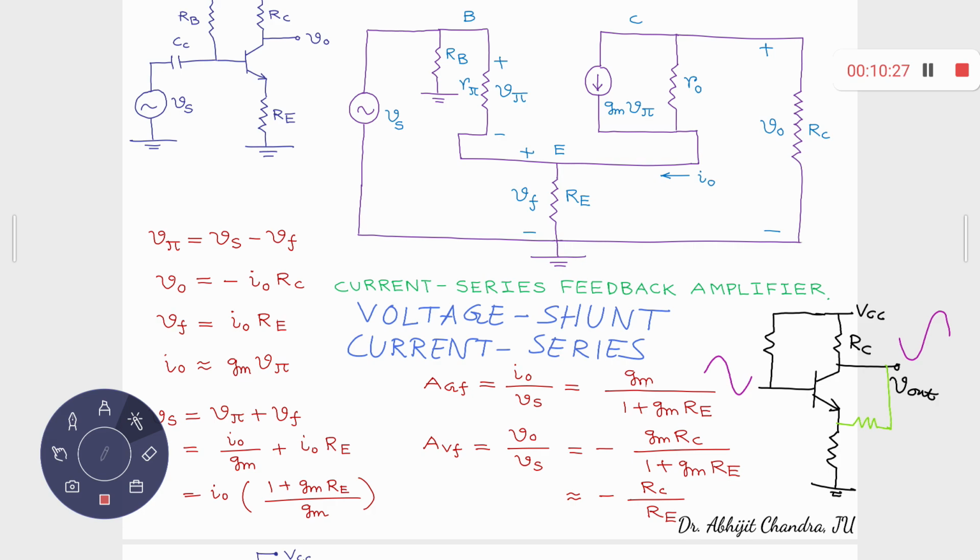And remember, this beta network consists of only resistances. In the feedback amplifier section, we will understand that this beta network that we discussed last day is composed of only resistances, no frequency selective elements. A resistance is not frequency sensitive, so it will only obey Ohm's law.